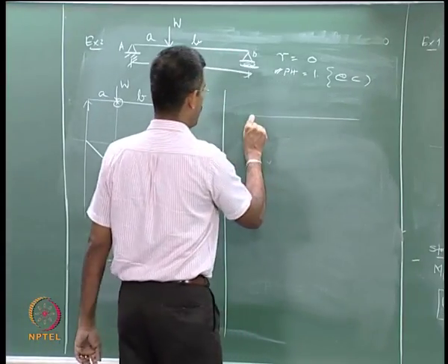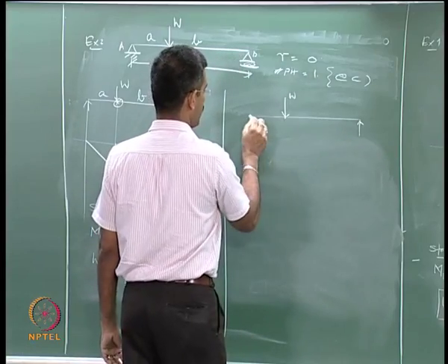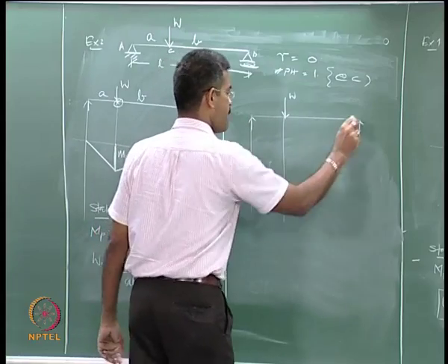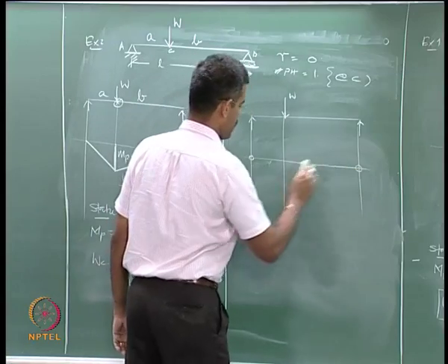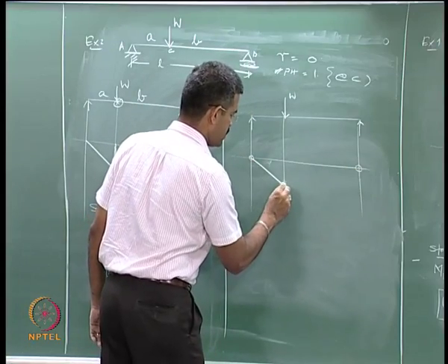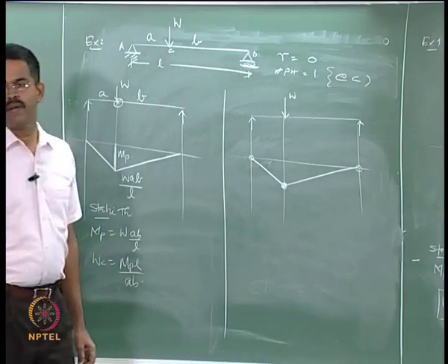Let us solve this problem using kinematic theorem. I have a structural hinge here, I have a structural hinge here, there will be a plastic hinge here. Okay.